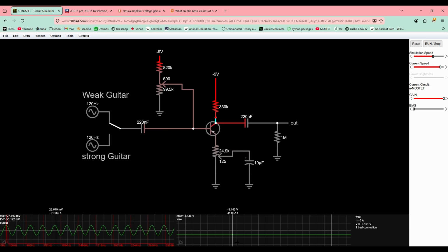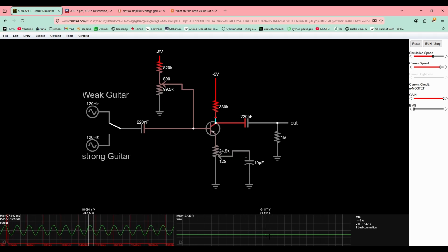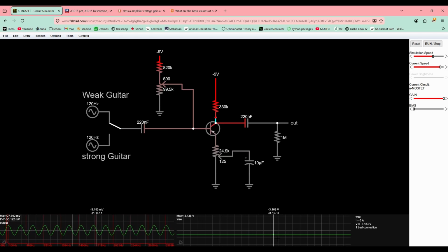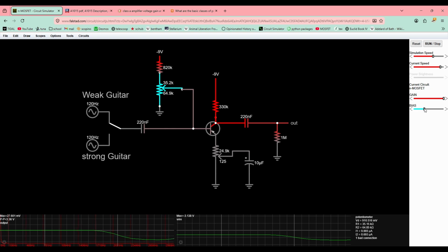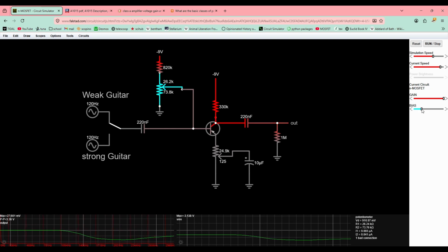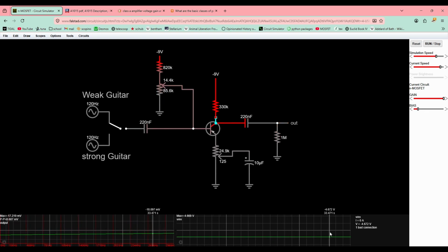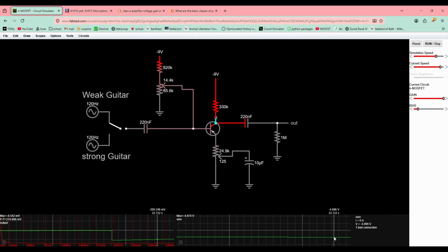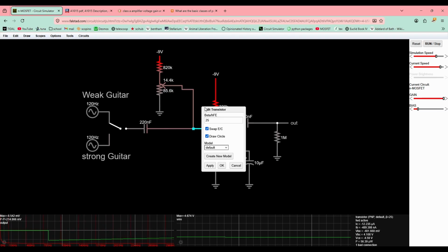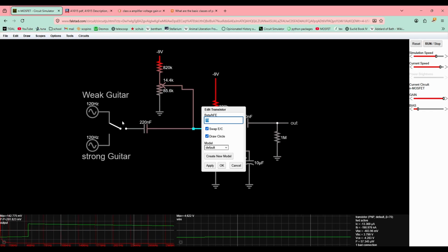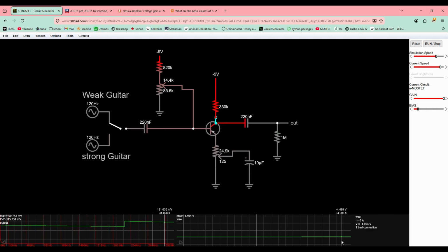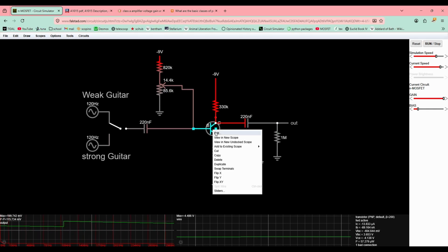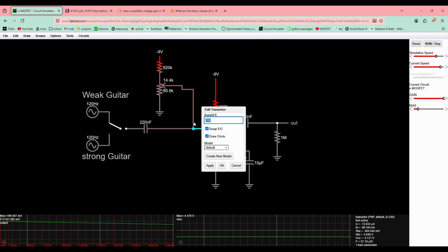So I'm probing this here. I'm going to change the bias so that this says -4.5, and in a bit we'll see how we're gonna do this with the real circuit as well. So now it says approximately 4.5, and what we want to see is that this is also 4.5 if we change the beta value of our transistor. So our preamplifier should not change a lot depending on this beta value, because it can change so wildly.